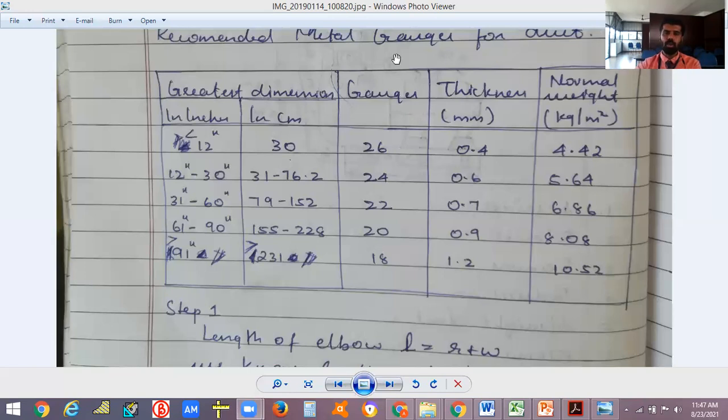If it is 225 into 250, 250 into 250, we'll be rounding it and we'll be giving. For the first 3 meters only. So it will be already, you'll be getting the sufficient area. No problem. If at all something is less, the noise criteria will be a little bigger, or the friction loss will be a little bigger.